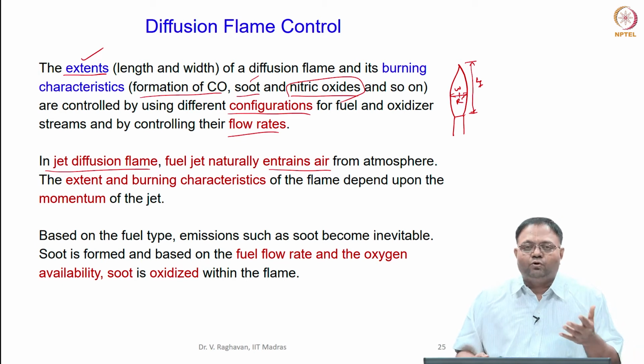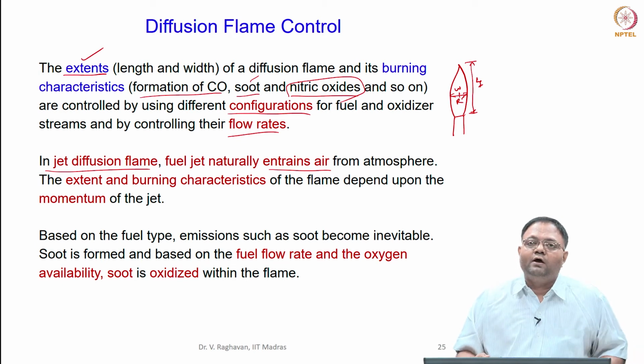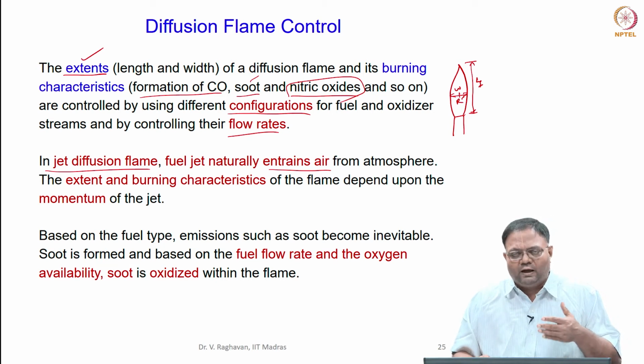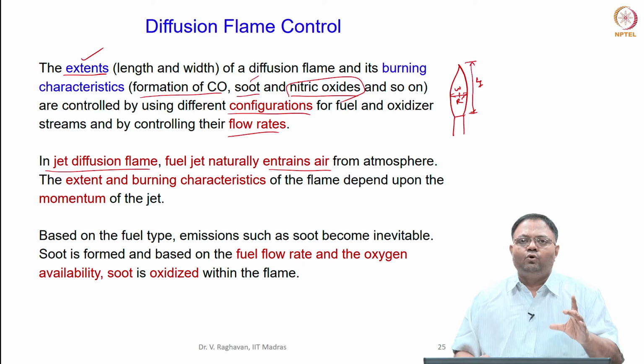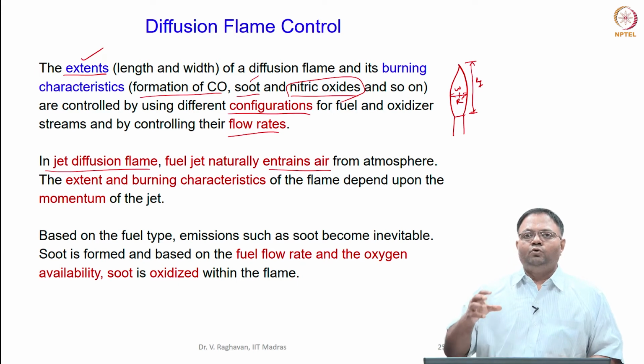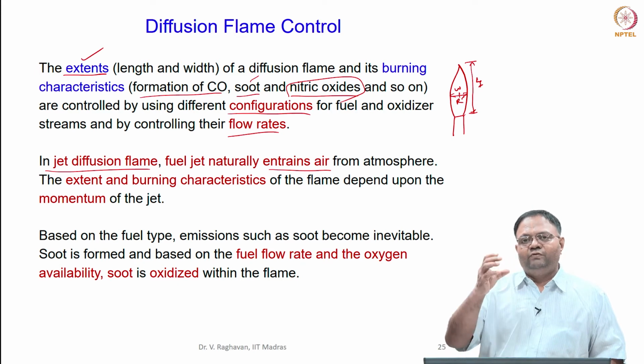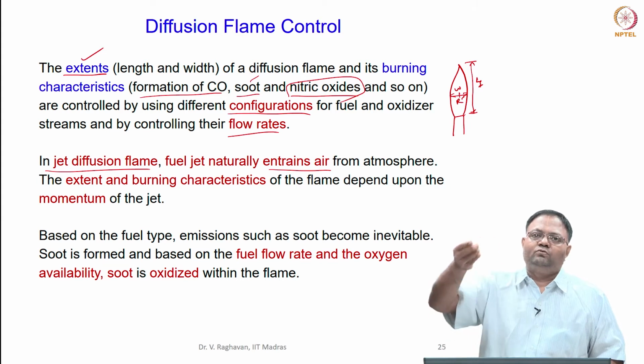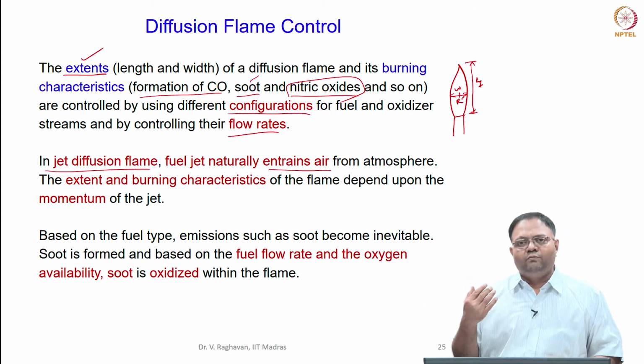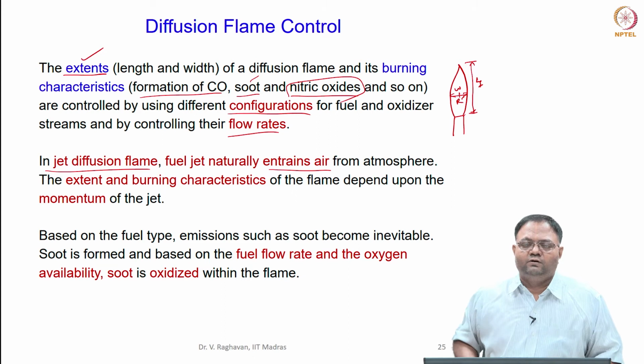When you want to control the flame length, only the volumetric flow rate of the fuel can be changed. But the flow rate has to be supplied in a given ratio. For example, if I want to operate the burner in a fixed ratio of maximum power to minimum power, then the flow rate also will correspond to that maximum and minimum values.